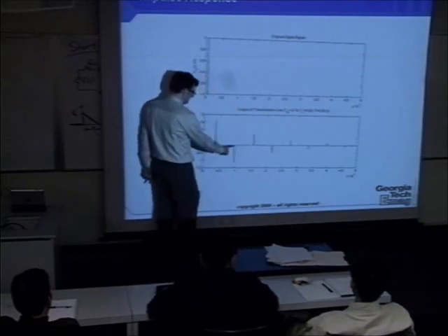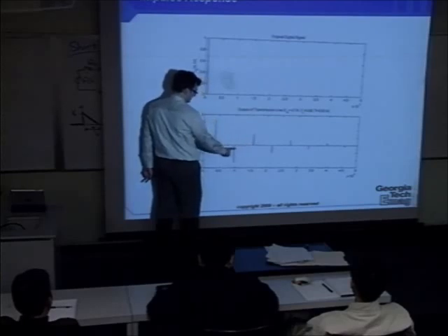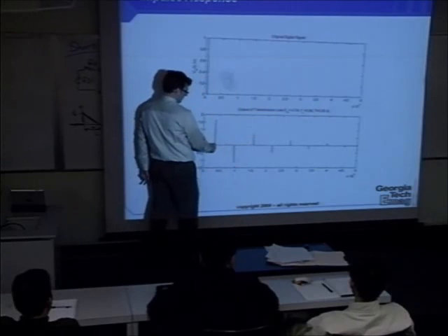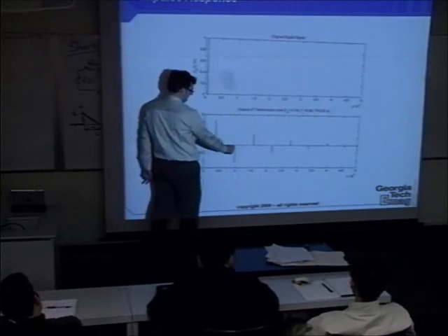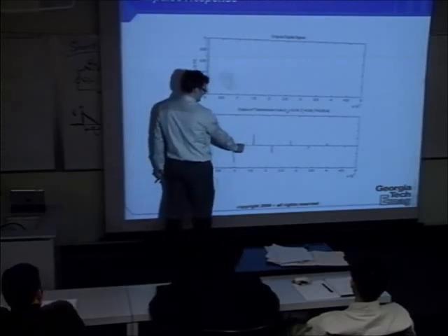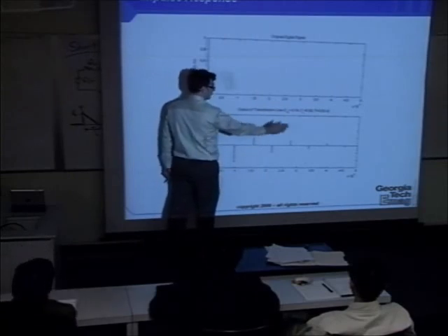Not surprisingly, each of these is a transit time, actually 2 transit times apart. So we have the first strike on the line, another transit time to get back to the source, back to the load. The second strike, another transit time to get back to the source, reflect back to the load, the third strike, and so forth and so on.